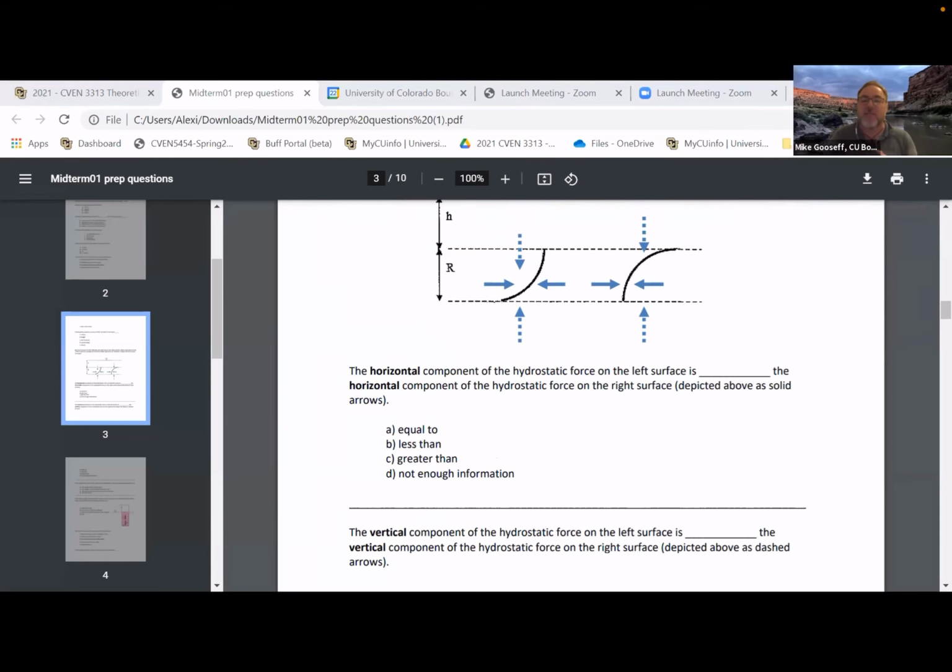But this is where the line of action part would become a little bit different. So if we were looking at now, when this is submerged underwater, it's fine to say that the verticals match each other top and bottom, but they might be different on the two forces. If we were to put these at the edge of a tank, let's say, the lines of action would be a bit different because of the distribution of pressure on one side compared to the other, right?